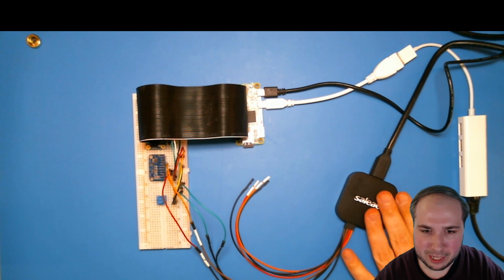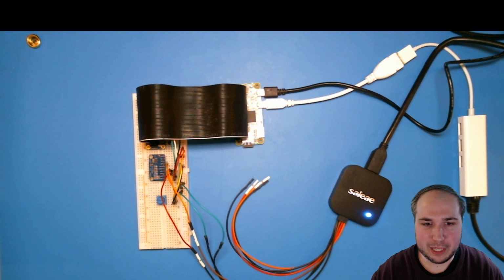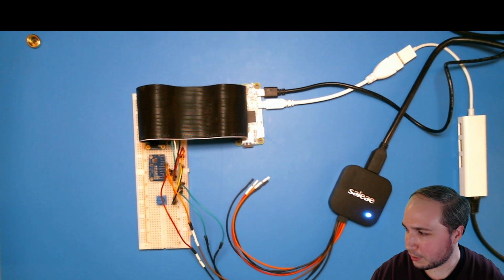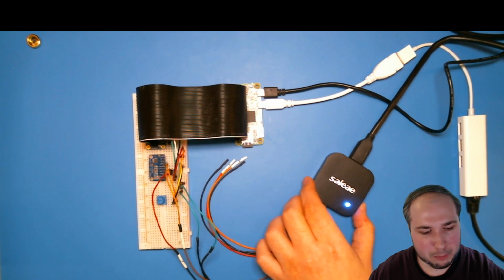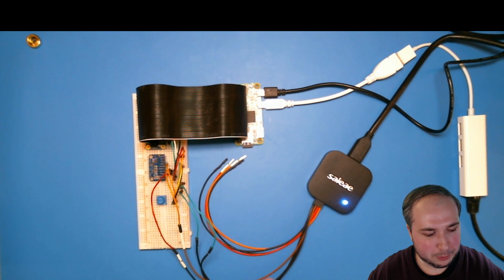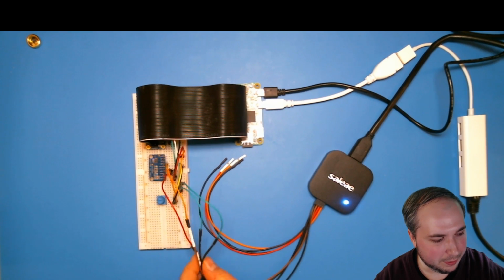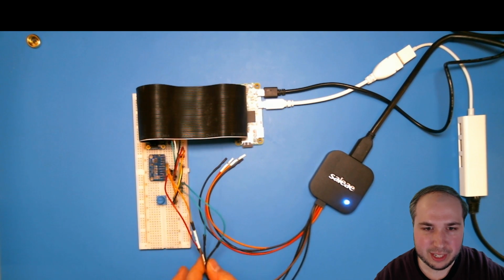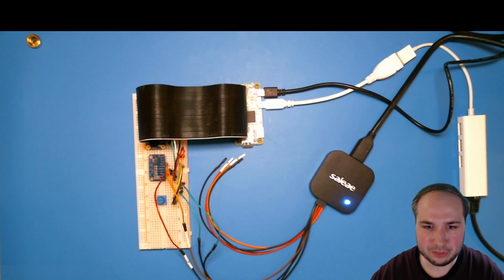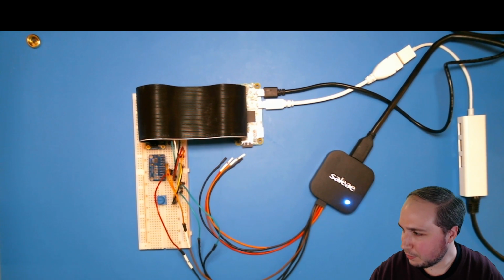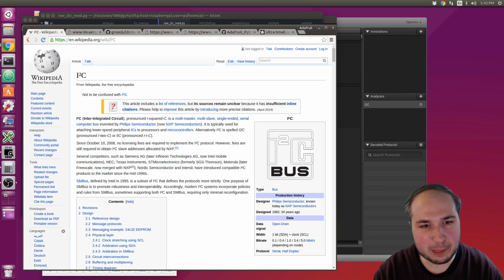And I've got it hooked up to a little logic analyzer, and we'll come back to this in a second. I thought it'd be neat to look at the protocol a little bit. We'll use this logic analyzer, which is almost like an oscilloscope, but more for reading protocols and digital signals. It'll sample the I2C communication bus at a pretty high rate, and it'll show you what bit values it sees, whether it's a high or low value. And if I jump real quick to the desktop, I basically got this up right here.